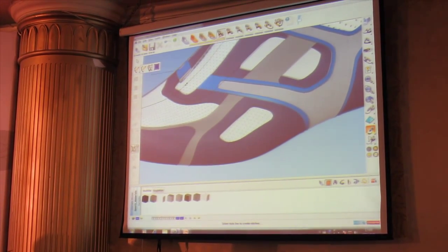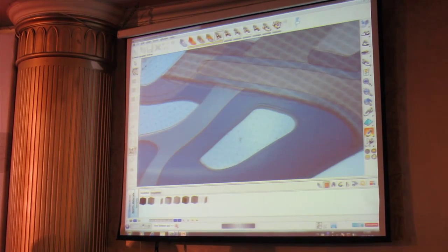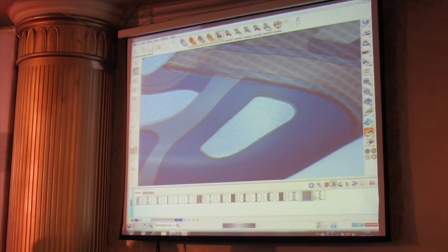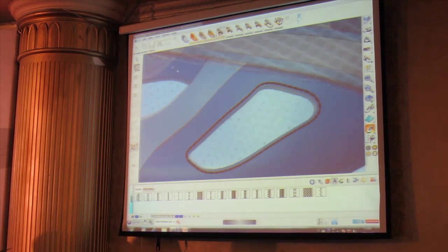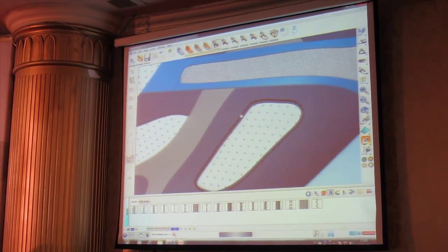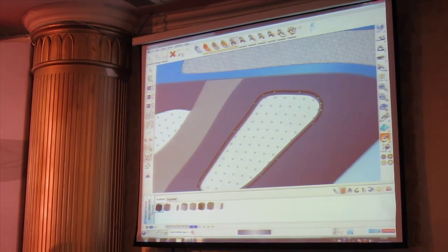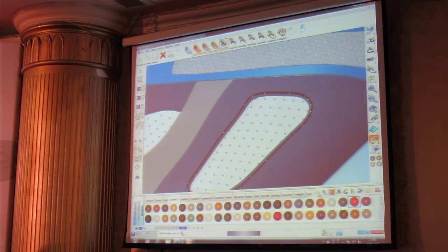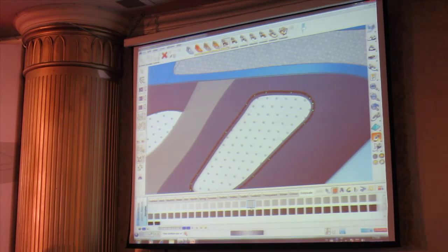I can make stitches in 3 different ways. I can make them from sketching, I can make them from an existing curve, which I'll do here. So I can select the stitching type, once again from the library, and I can then select an existing curve. You can see the stitch pattern is created for me following the curve that I've selected. Now these stitches are fully 3D, so if your design is intended for use with rapid prototyping, then you can get a proper 3D stitch effect from these stitches because they are 3D shapes.